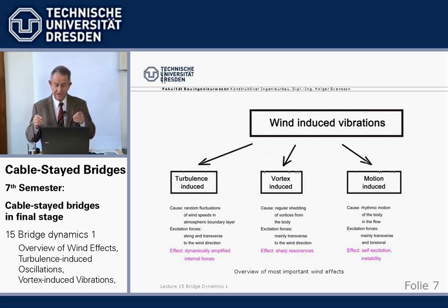The next one is periodic vortex. Vortices form behind a bluff body. Theodore von Karman found that out. And this periodic vortex shedding creates small forces, but with time they can also excite the bridge.